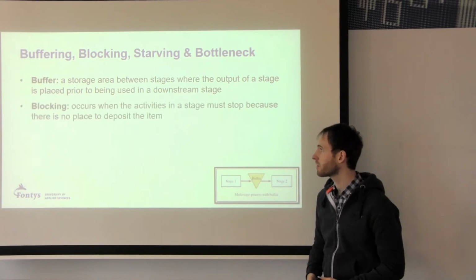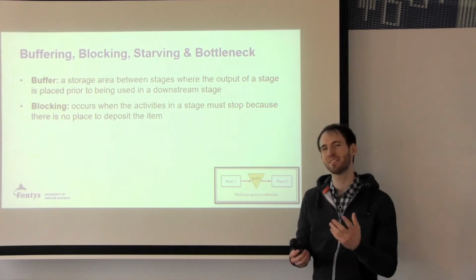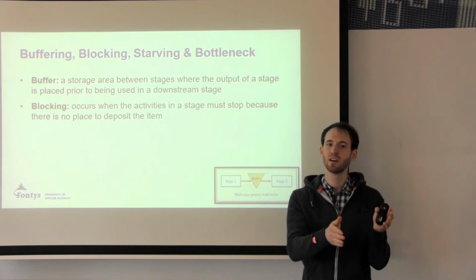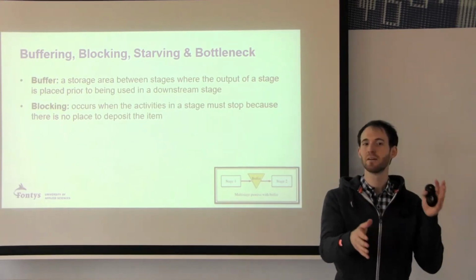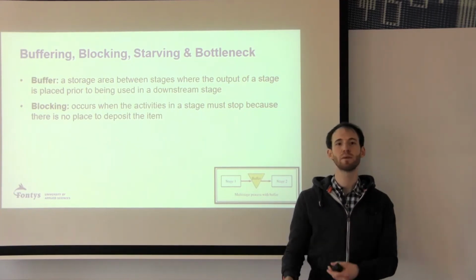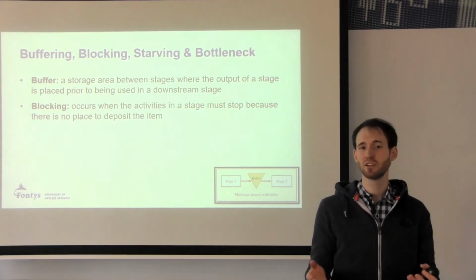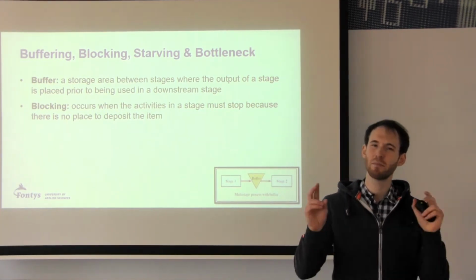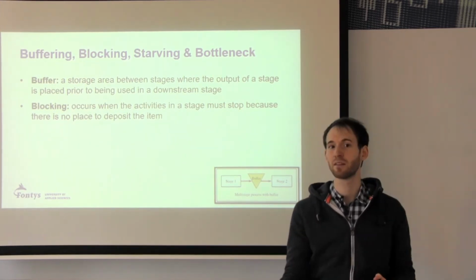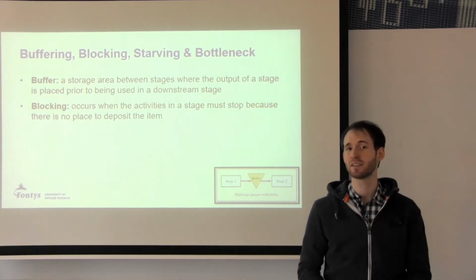Then we have blocking, which actually is a very bad buffer, basically. Now you can't really say it's a buffer, but it means when you have, let's say, a stage in the process. Let's say you produce certain car parts, you produce them and you want to put them in inventory, but there's no space to put them. You actually have to stop stage one. You have to stop the process until there's space available. And this is very bad. It is also kind of a buffer, but it's a buffer that is not planned with. It's a bad buffer, you could say, because it stops the whole process.